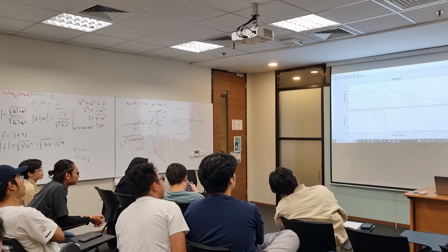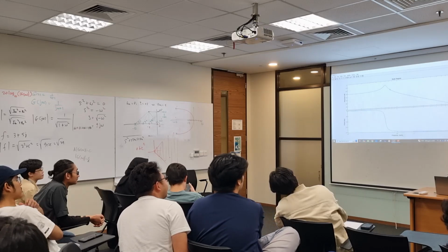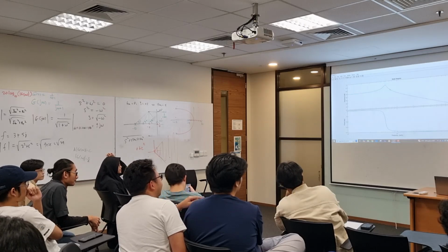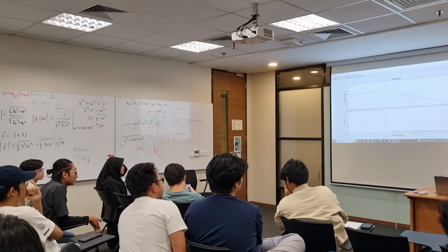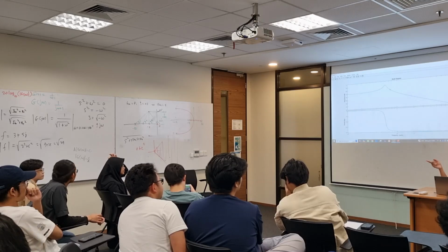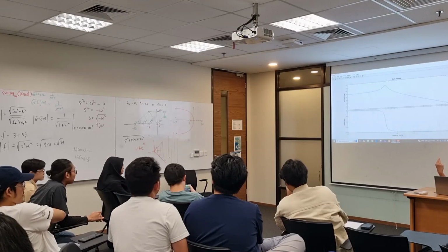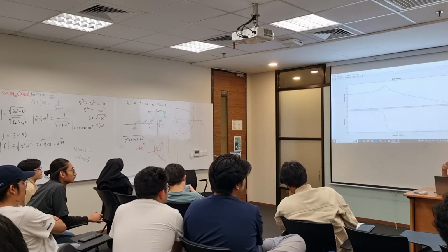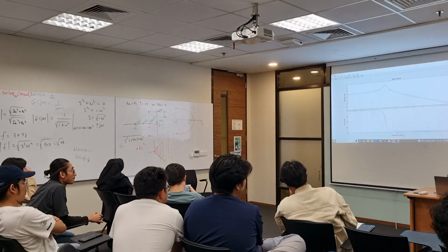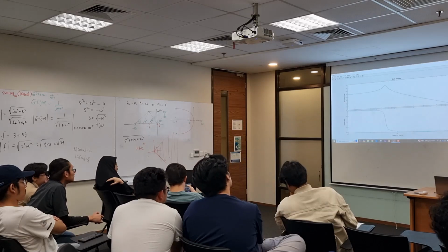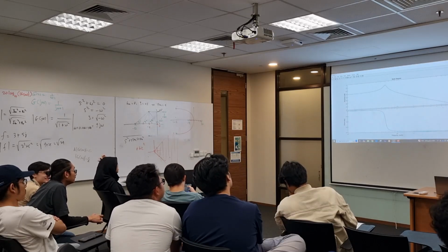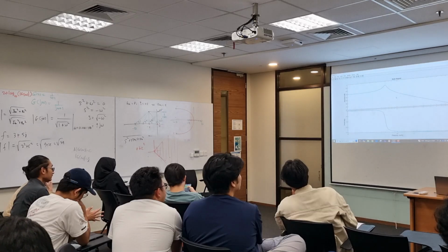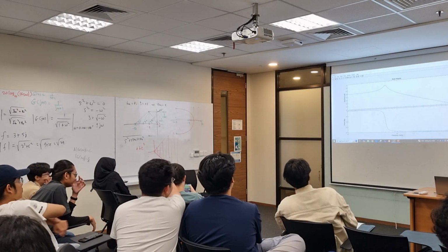What's the input and what's the output? What is the input to the system? It's a sinusoid. Now the input is not important, because we are just getting the G of j omega. You see, G of j omega is just the ratio. The input magnitude, the input amplitude, is not important because the magnitude here is giving you the ratio between output and the input. This part is the ratio.